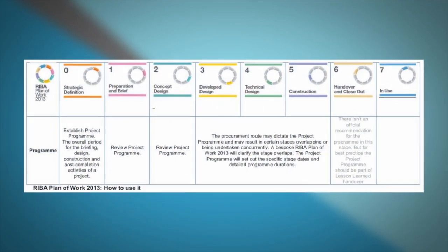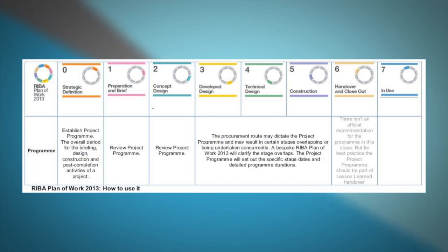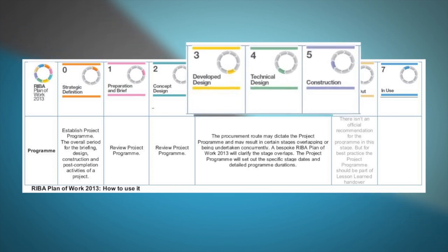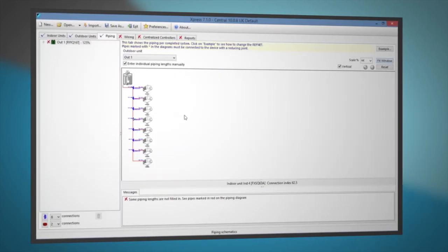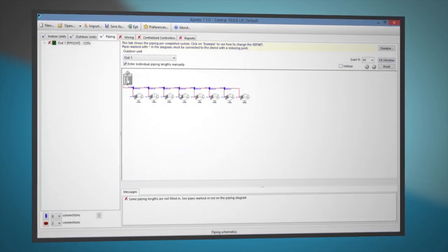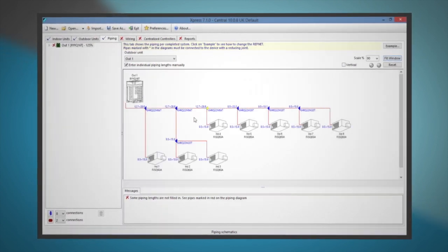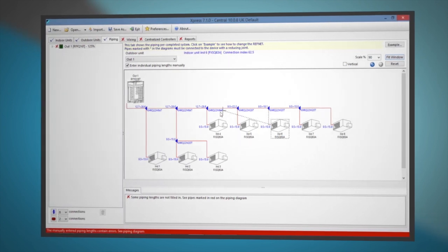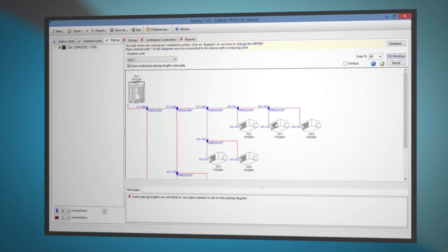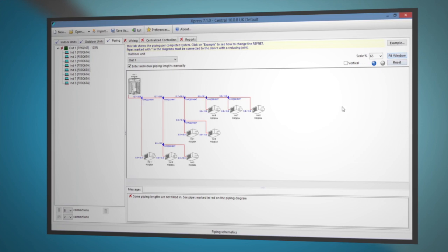The creation of building schematics is a necessary part of the building process, all the way from conception through to handover. Throughout this process, designs change as architectural revisions are made and the building services become more defined over time. This means that drawings often need to be revised to accommodate these changes. And when a system such as VRV is being used within the building, the pipework routes need to be considered to ensure that pipework limitations are not exceeded during the revision process.